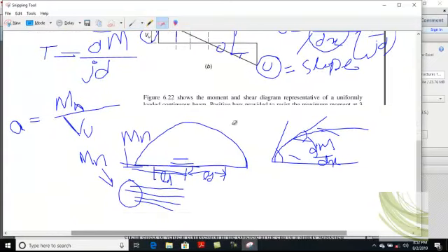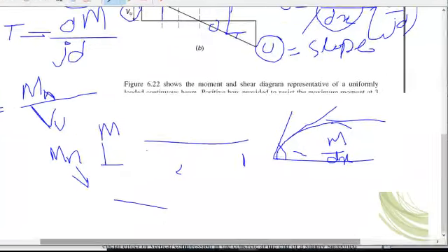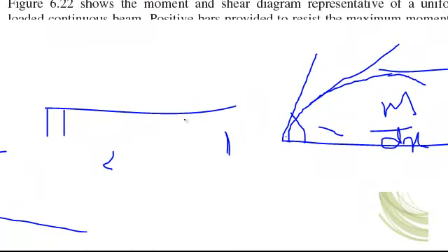Whenever we are dealing with simply supported beams, at the support this kind of problem also occurs, and inshallah we will check for this moment as well. At a simple support there are supports, and the moment starts from the support like this, so the support moment is zero.